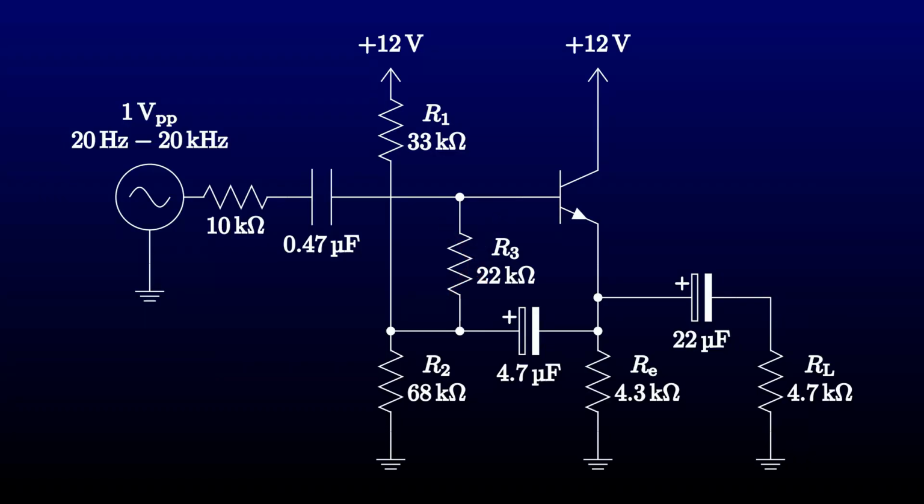Another way to look at what's going on here is that the capacitor is adding the output AC voltage, which is the same as the input AC voltage, to the middle of the voltage divider. This feedback is a little strange. It's as if the circuit is pulling itself up by its bootstraps to raise its input impedance. And this technique goes by the name bootstrapping. You'll see the capacitor referred to as a bootstrap capacitor.